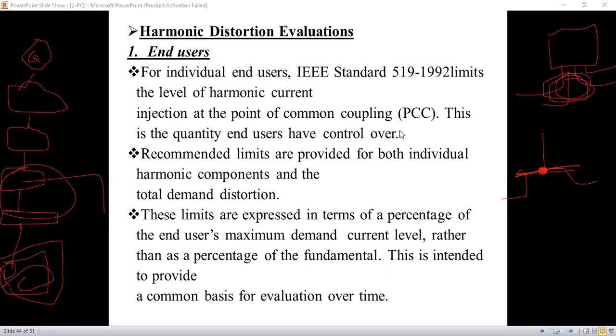For a heater, normally we will connect to the 6 ampere only, but the actual current rating required is 15 ampere. We call that one, or 16, standard 16 is there, but in the switches in the shops, we consider the 6 ampere switch and the 15 ampere switch. Why? Because of the load. Suppose we use a 1 kilowatt, 1000 watt iron box.